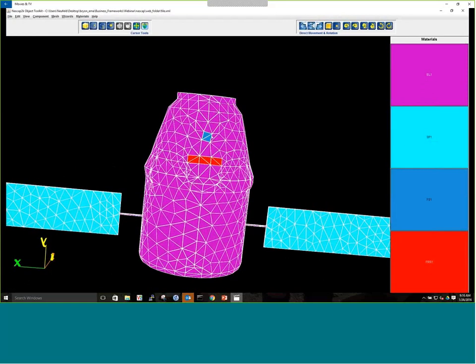And one of the nice things is the materials, since they're already assigned, you don't have to go in and assign them element by element. You can see how tedious that process might be if you had to go in and select all your elements to assign materials to. Here in the EMA 3D format, we do it just region by region, so it's much quicker that way. And then you can also modify your geometry and re-export it very quickly, and you don't have to feel the pressure of, well, I don't want to have to assign all my materials again every time I need to change the size of a window or add an antenna or something like that.